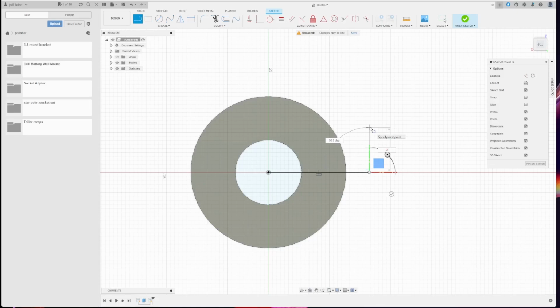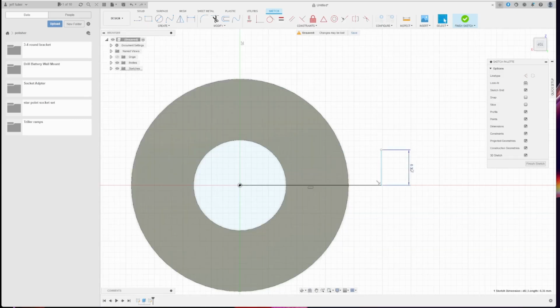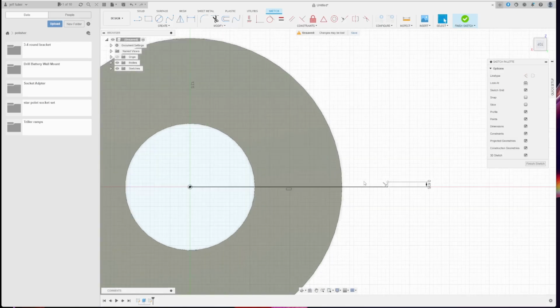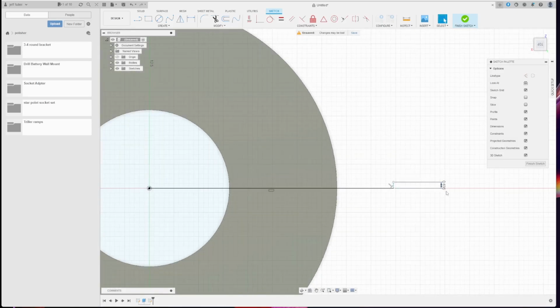So I'm going to put 0.25 here for this vertical construction line, and of course call it inches. Now, I forgot to add an extra 0 here. So I put 250 thousandths, which we again decided was 1/4 of an inch, and I wanted 25 thousandths. So here I just clicked on the arrows and I'm able to adjust it, and that's our construction line.